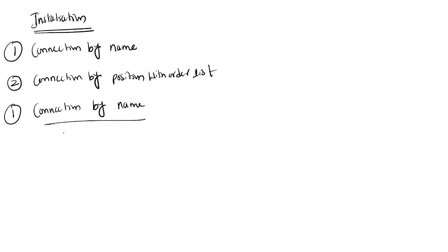So you need to declare inputs. I'm writing for the test bench. In the test bench, I'm writing module test bench for the AND gate, module TB. I declare inputs, which can be wire data type. For the connection by name, the syntax will be like this.